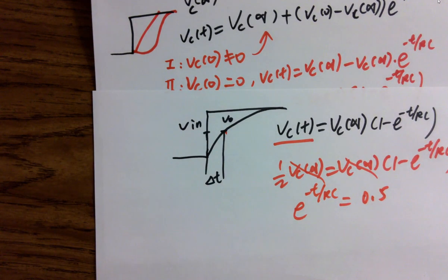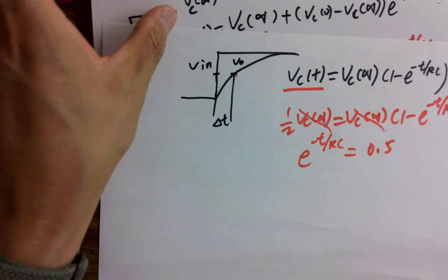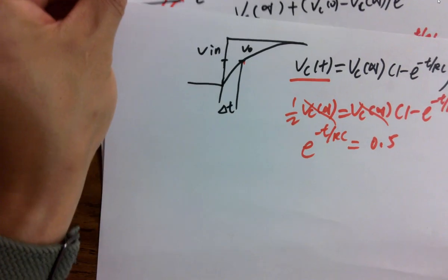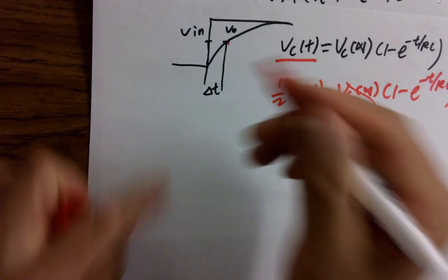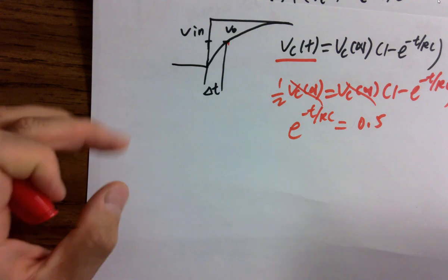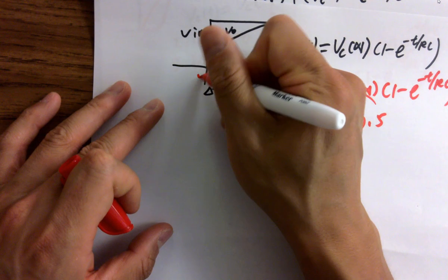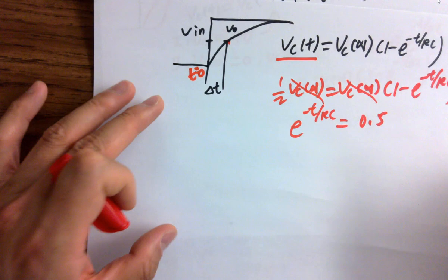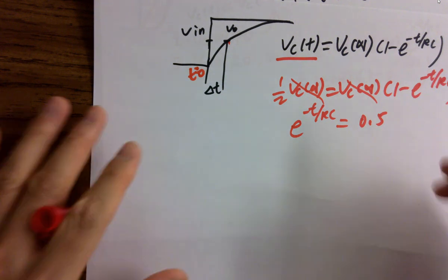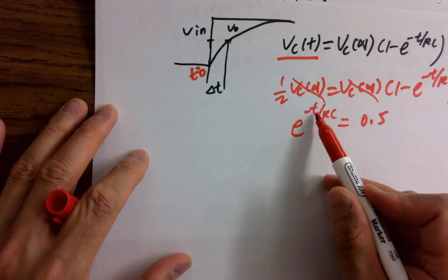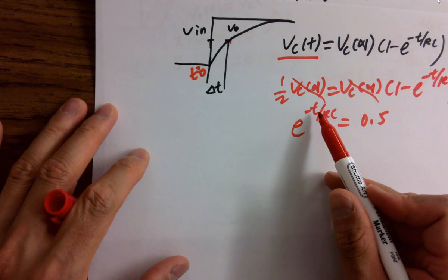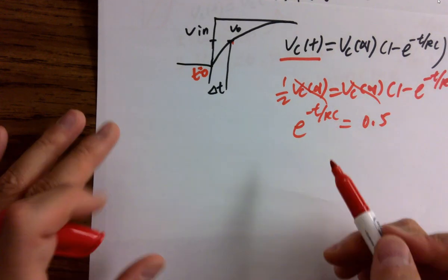That's great, it's a constant. So now we can calculate t. You are saying, hey, it's a delta t, it's not just one t. We're assuming this is time 0, right? At time 0, we close the switch. So it's basically t minus 0. So this t over here, t minus 0, is delta t. So the result will be delta t.